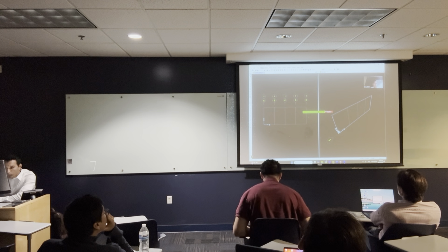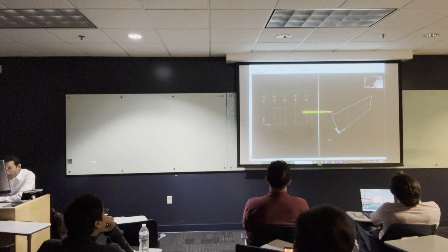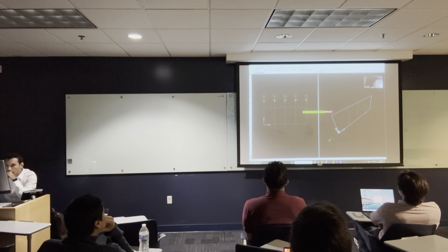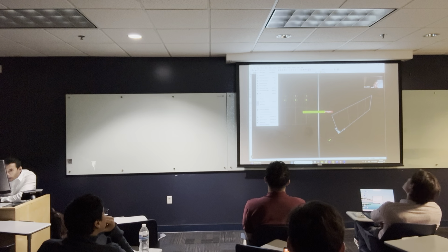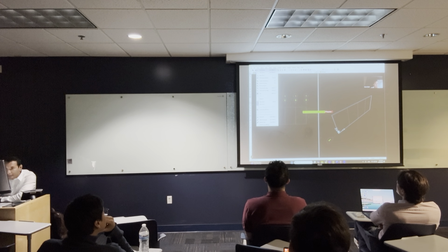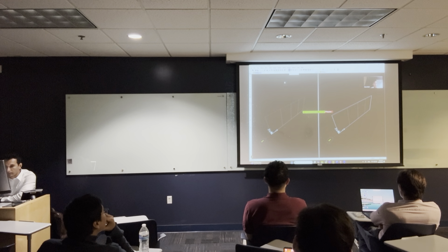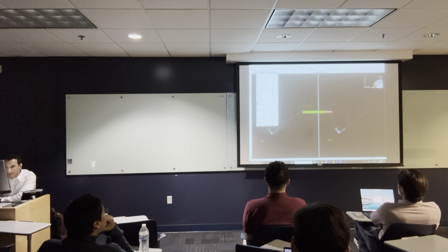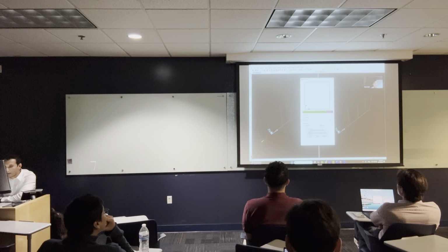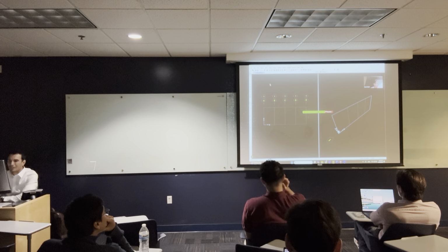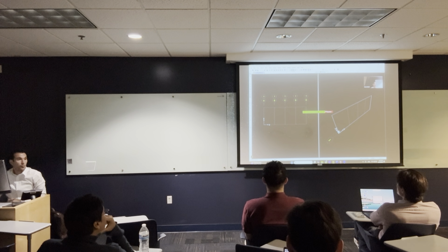Or you go to view, here, and you can set the 3D view or you can set the 2D view, but I would rather use these two. So let's say you are here, you made it 3D. You can come here, view, and set 2D view, and then you can pick what 2D view you want. If you want XZ, you can make XZ, and then you say, okay, it's going to be X. But that's too much work. I would pick it from up there.